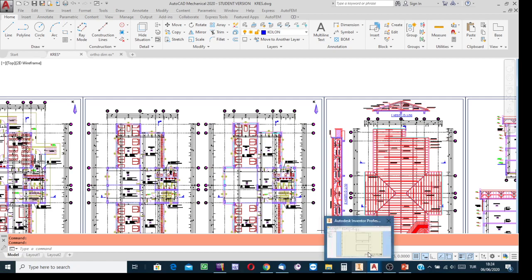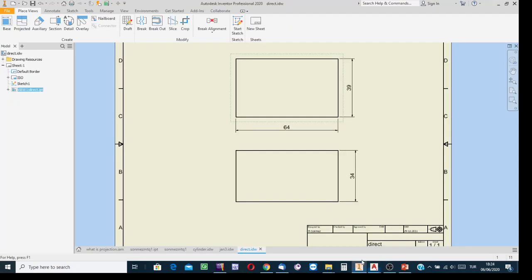But in mechanical engineering applications, the object may not be in a rectangular prismatic shape. It may even be a very complex geometry. And the only thing to do in case the object is complex in shape is to draw the views, create the views at their standard locations. Never break the link between the views. The reader should be able to find the views at their standard locations, so they can much more easily pass through the reading stage.